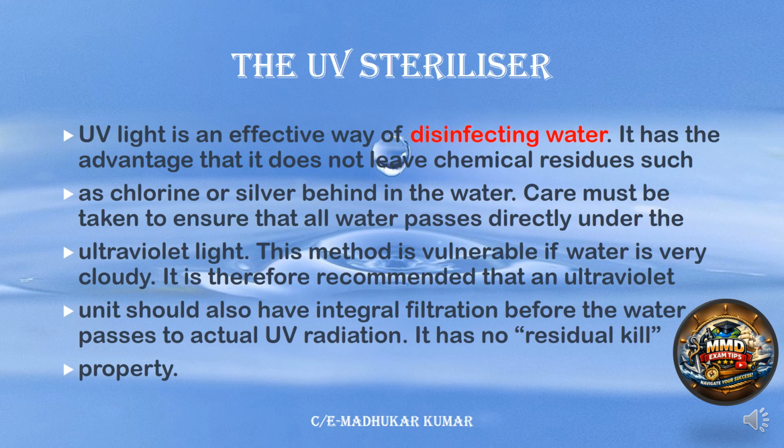It is disinfecting the water. It has the advantage that it does not leave any chemical residue, as chlorine and silver do. Care must be taken to ensure that all water passes directly under the ultraviolet light. If it is like that, then the method is useful. But if the water is very cloudy, then there is a problem.